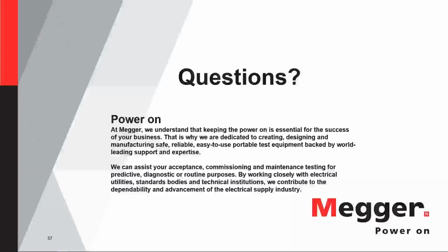Okay, thank you, Dinesh. Next question: what is the accuracy of our unit and when do we need to recalibrate it? The accuracy listed for the OT 60 and 80 PB is plus or minus 1%, plus or minus 2 digits. And remember, it's a voltage meter, and the resolution is 0.1 kilovolts. So again, the accuracy will be plus or minus 1%, plus or minus 2 digits. The recommended calibration is every year.